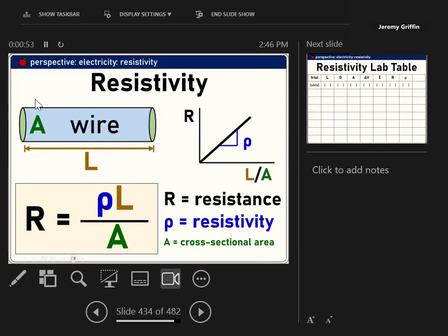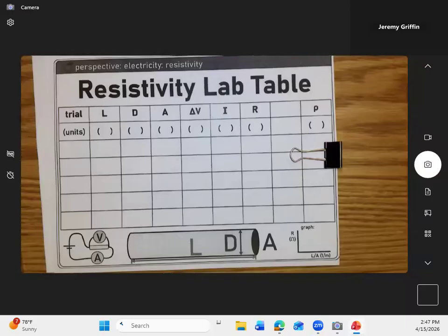What about this? What if you take this cross-sectional area? You guys see this cross-sectional area? And what if you started off with a real skinny wire, and then you made this cross-sectional area bigger. So this A is getting really big now. Now what's happening to the resistance? Smaller. Yeah, it's getting smaller. It's getting less and less, decreasing. There's an inverse relationship. And what ties it together to make an exact formula is this resistivity value, which is some material property, like copper is different from aluminum, different from Play-Doh. And Play-Doh is what we'll be looking at over here.